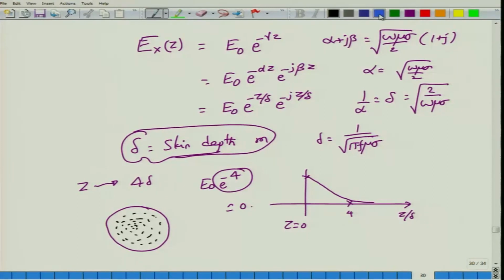But at very high frequencies, the current is confined only along the edges within this particular material. At higher frequencies the current is just confined to a thin strip, and the width of this strip is given by the skin depth delta, and this width keeps decreasing. When the frequency goes to optical frequencies, the skin depth will be a very small number, provided you keep the same values of mu and sigma.